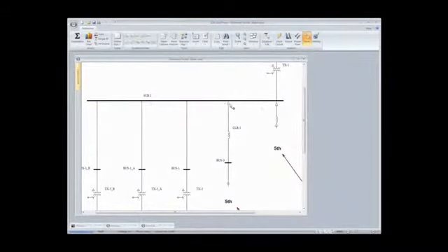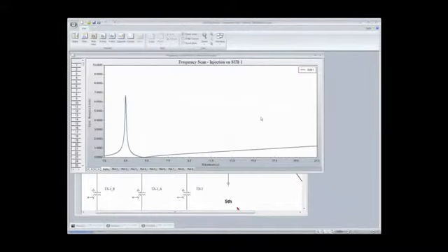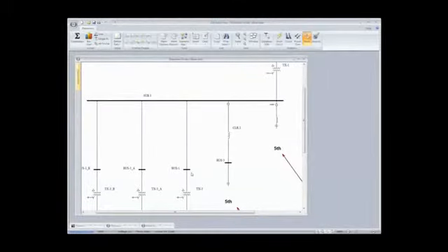If I use this one, broken out into separate components, I can get identically the same simulation, about the 4.8 harmonic sitting right on the third. So these two modes are completely comparable with each other. If you want to break it out into separate components, you can. If you want a single component, you can do that as well. In this case, if I do a summation calculation for my distortion, notice that I'm plotting root sum square voltage here.